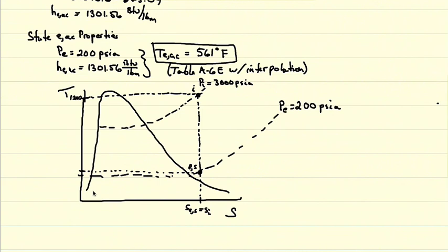which we actually didn't look up, and I don't have the thermotable with me right now to verify what it is. All the same, we can also draw on here our exit entropy, and we can show that our actual exit entropy is higher than our ideal exit state entropy. So we can draw that here and say that this is our actual exit state, since it's at a higher entropy. And so our process actually looked like this. That's what our actual process basically looks like.